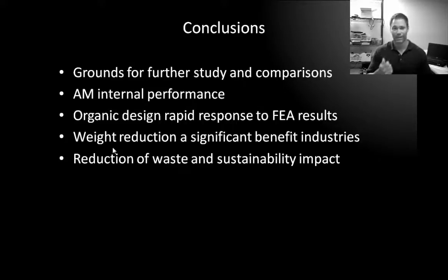But we did see that the organic response to the FEA results, and by organic we mean designing more organically, just pulling and shaping where you needed material, had a very large benefit. Obviously, near 40% weight reduction is a significant deal. And reduction of the waste associated with conventional manufacturing, we weren't creating scraps, we weren't cutting material out. We only needed the material we needed, and there are sustainability benefits for something of that nature going further.